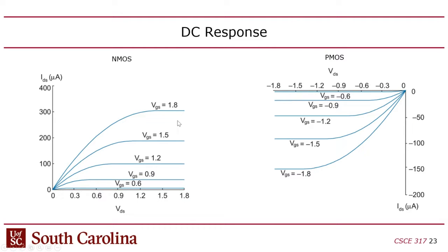So basically, you want to have the gate source voltage as high as possible in order to delay saturation mode for as long as possible, which is why these chips are binary. Ideally your gate voltage is always going to be binary. It's going to be 0 or it's going to be VDD. Generally speaking, you want to keep the gate voltage either all or nothing, essentially.